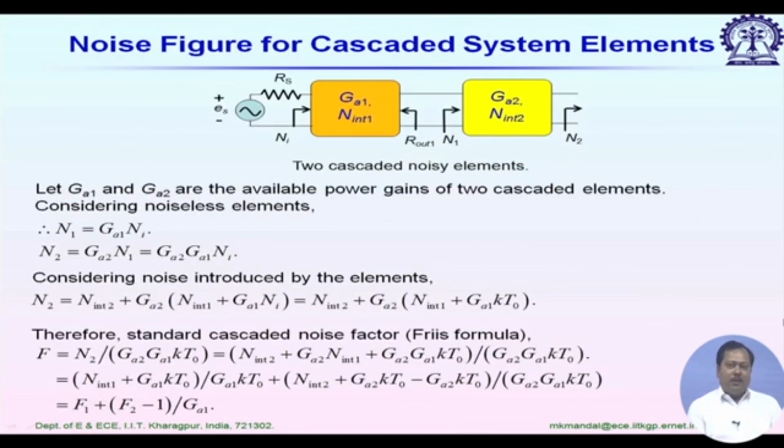So now we learned how to calculate the overall noise factor of a receiver, and if we simply convert it to decibel scale, then we call it the overall noise figure of the receiver. It will determine the noise floor below which the receiver can't detect any signal power.